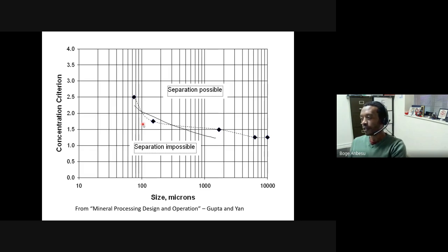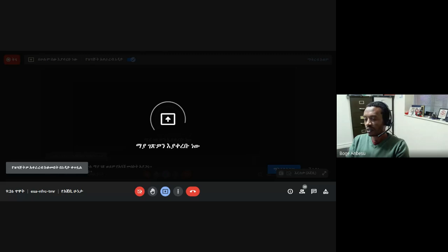Okay, I think that's better. So if you look at particles that are below 100 micron, usually gravity separators struggle with fine particles. Simply because with fine particles, the differences in density are not significant, especially when it's mixed up with water and particles are moving sufficiently well in the separator.